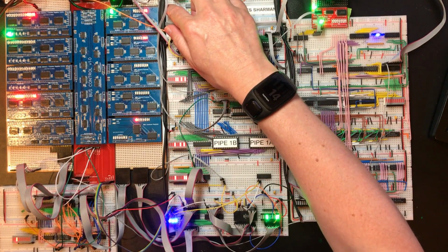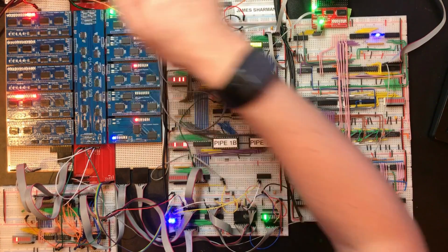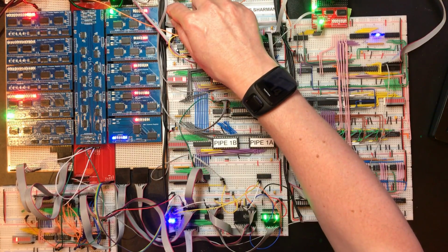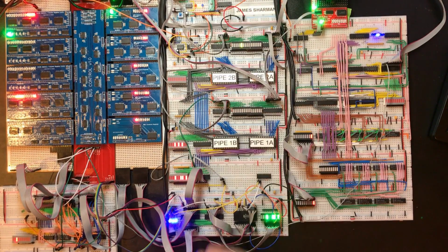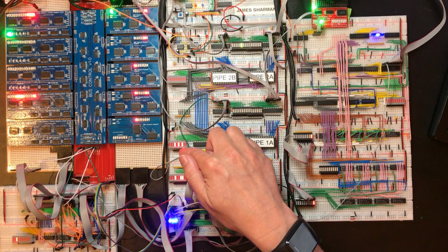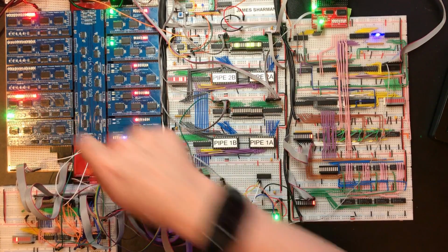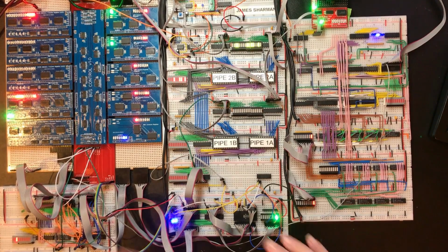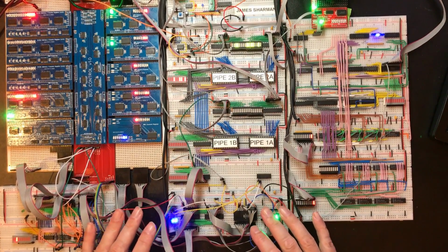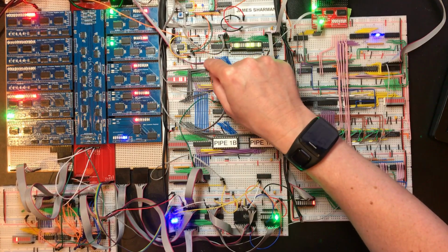So this should be the mov c, tx, and the increment hasn't happened. So there is our mov address of tx, a, so our memory write of a. So we're getting a out, and then the write of b to the address of si. Okay, well that's cool. We've definitely proved that the memory bridge is working right, but this is slightly worrying.